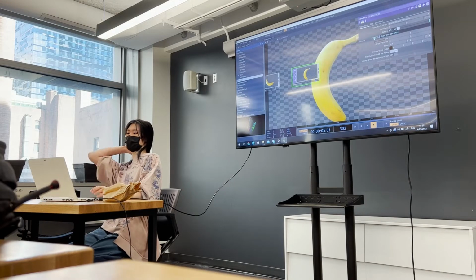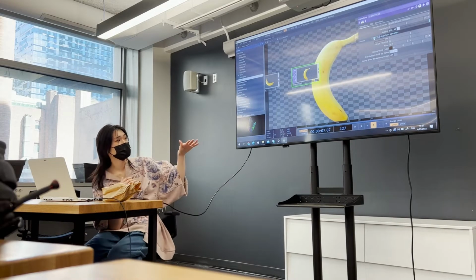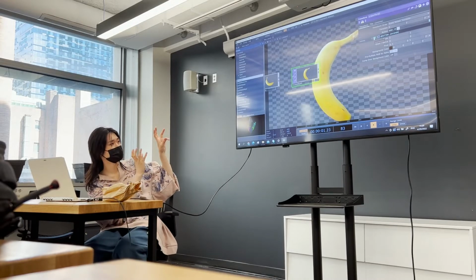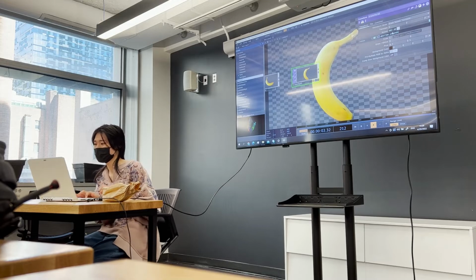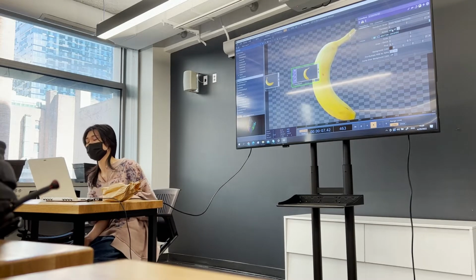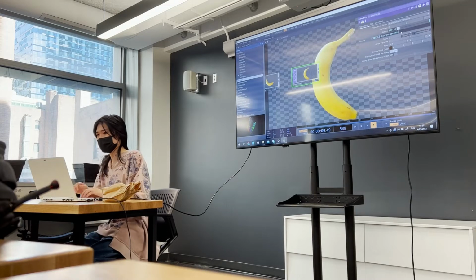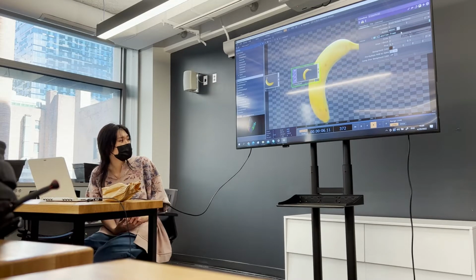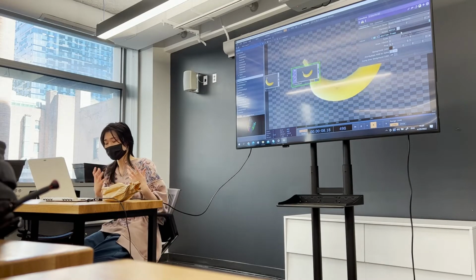This means that absTime.seconds is the number of seconds that have passed since you opened this project. Here, I opened it about 10 minutes ago, so it's like 600 seconds. Another one that's pretty common is absTime.frame, which is the frame count that has passed since the opening of this project.